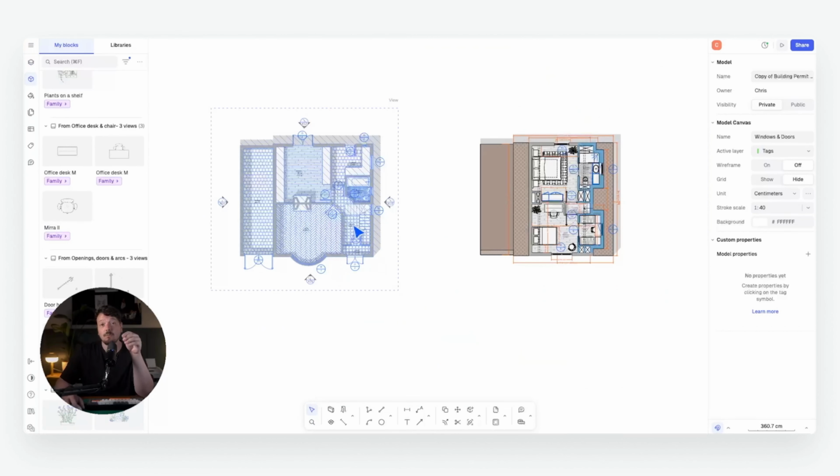So with all those windows and doors tagged, we're now going to decide which are being replaced and which are being retained, because they will have a different reference point. So for the project, we are proposing to change all external windows and doors, and that's to increase their U value. So at the moment, they're just old single glazed timber frame windows, and we're looking to increase the thermal properties and introduce double glazing to those.